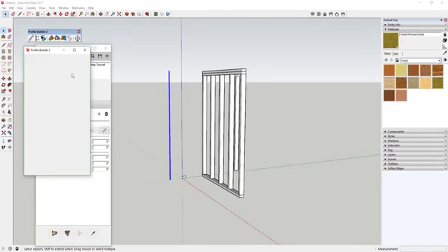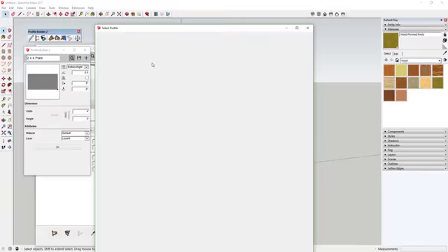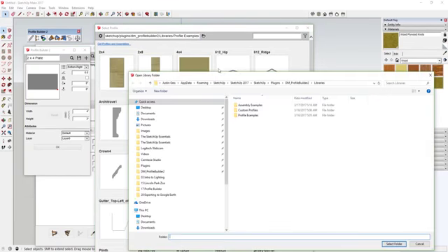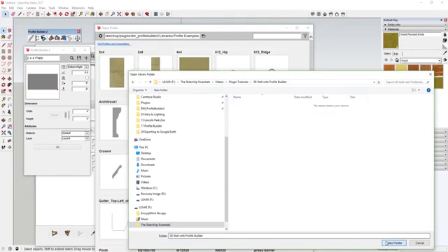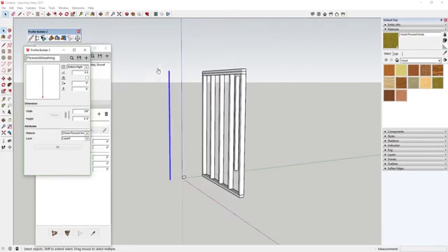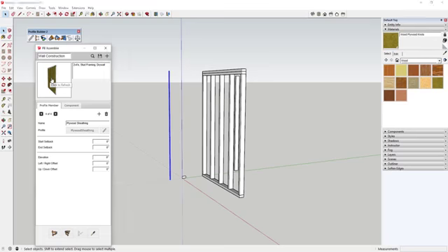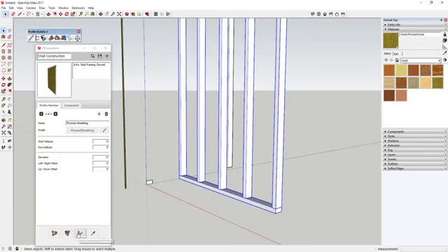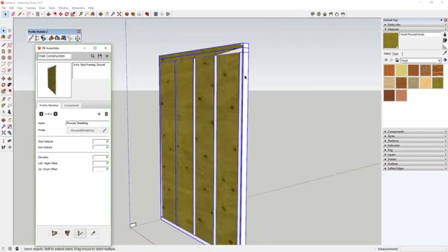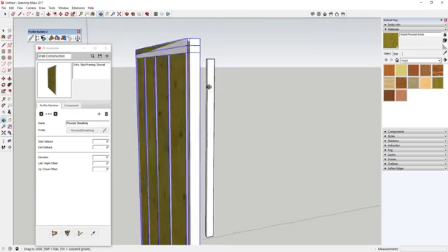You're just going to select that in the same way that you selected it before. So come in here, find your folder, select that folder, and then click plywood sheathing and hit OK. You can see what that does in your object right here is it adds plywood to your object. If I click on this and click apply assembly attributes, you can see it adds that plywood to this face.